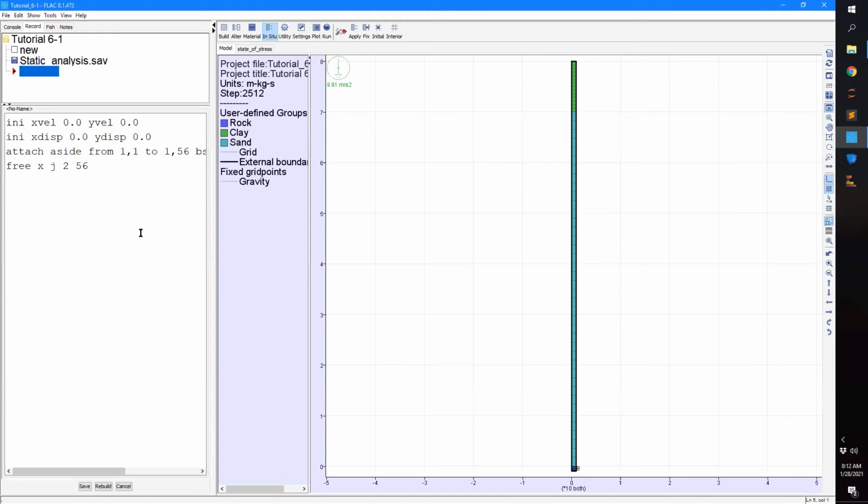Okay, next thing that's important is that we're going to be doing a dynamic analysis, and we need to specify some type of damping. Thankfully, the clay and sand are modeled with the UBCHYST model, which does capture hysteretic damping at low shear strains. But nevertheless, it is important for us to have a little bit of damping. The damping frequency that I have found generally works, and I referenced a paper previously in the constitutive modeling notes, is around 2 Hertz.